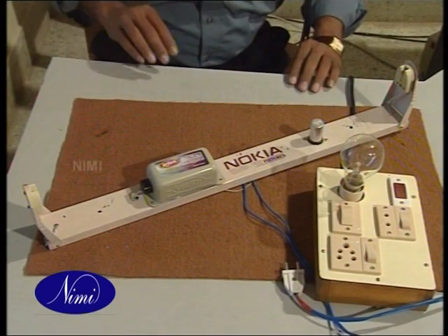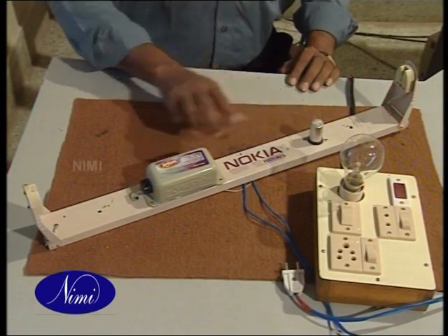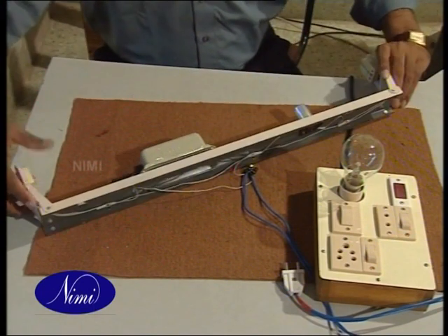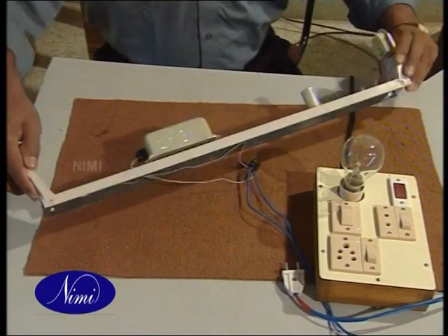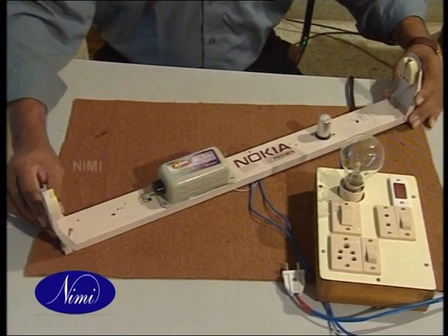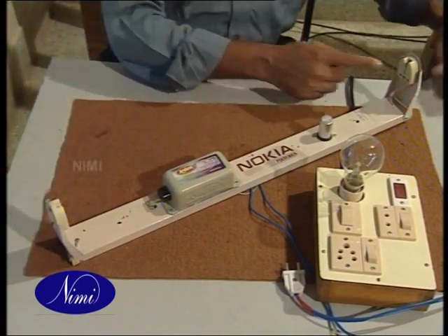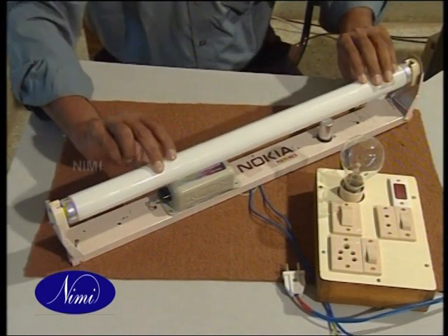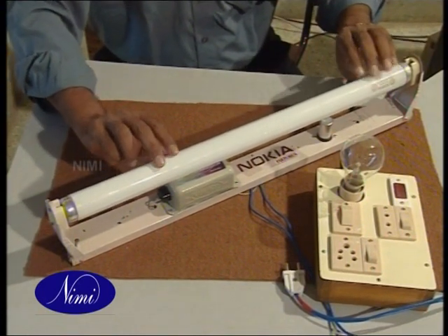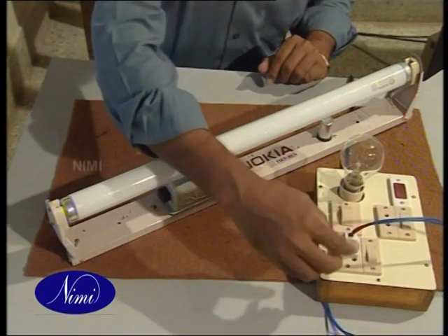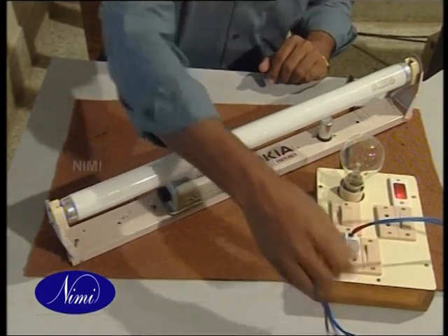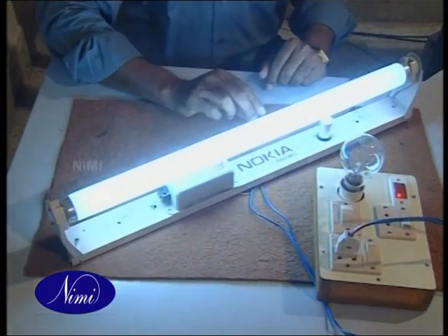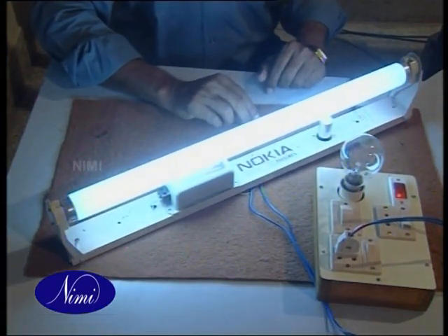This is how you assemble a fluorescent lamp unit. After fixing the accessories in the fitting base, give firm connection to the terminals by using a flexible PVC wire as shown in the circuit diagram. Next, insert the tube lights, turn them by a quarter turn in their position and switch on the power. By adjusting the tube lights a bit, you could see the lights glowing.